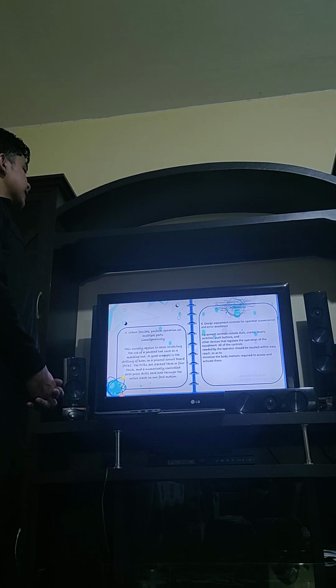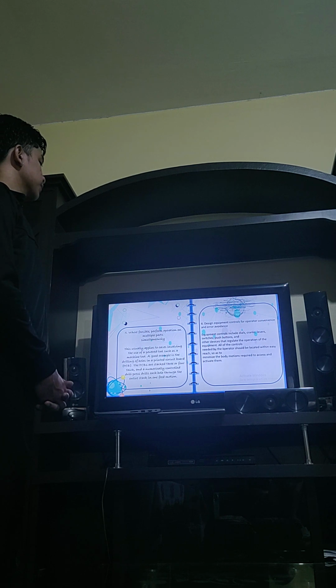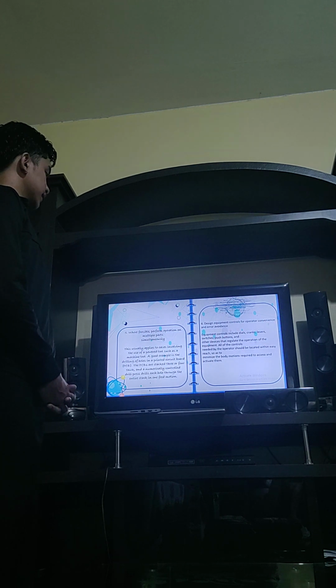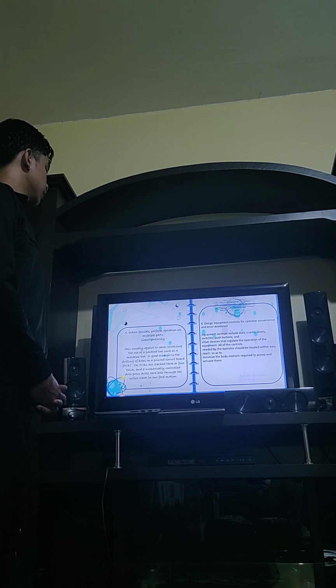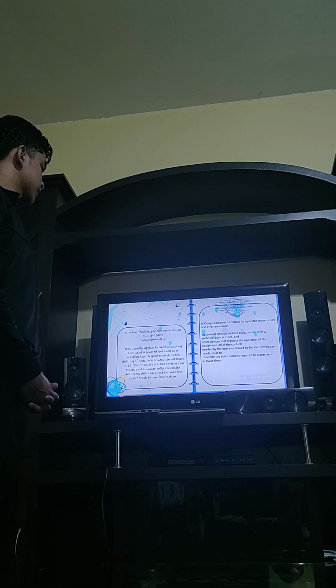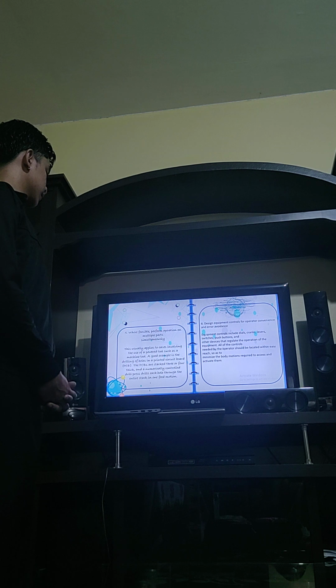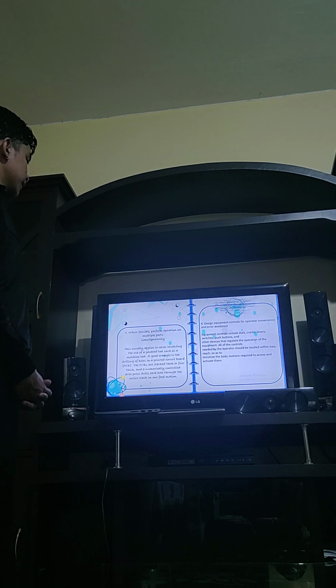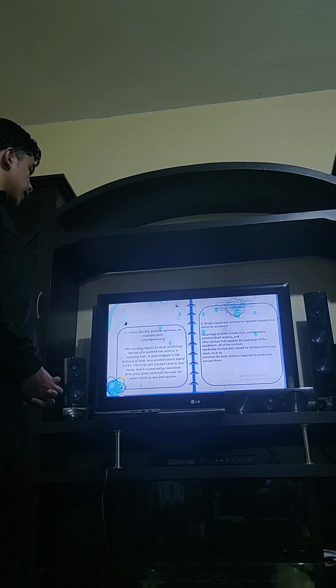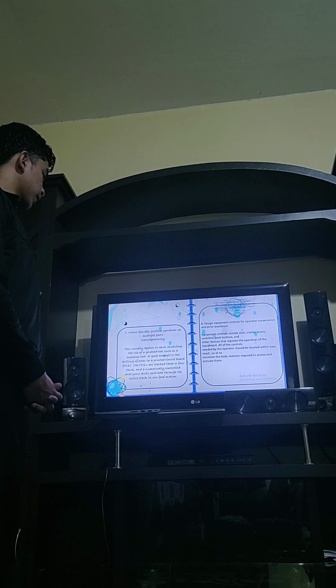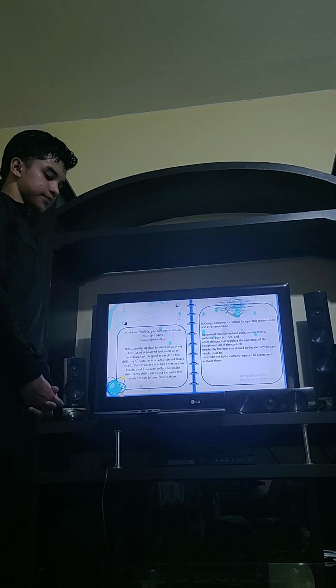Number 5. Where feasible, perform operations on multiple parts simultaneously. This usually applies to cases involving the use of a power tool such as a machine tool. A good example is the drilling of holes in a printed circuit board or PCB. The PCBs are stacked three or four thick, and a numerically controlled drill press drills each hole through the entire stack in one feed motion.